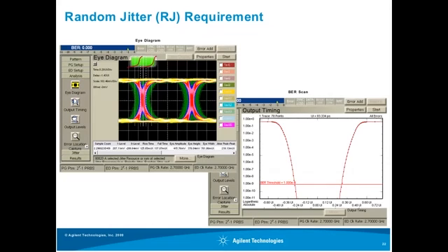So I promised some screenshots. Here they are. This is an eye diagram on the left side of a random jitter measurement, and you see in the middle, most of the edges are on top of the Gaussian distribution, and the more you get towards the tails of the Gauss, the fewer events or edges you see in that eye diagram.